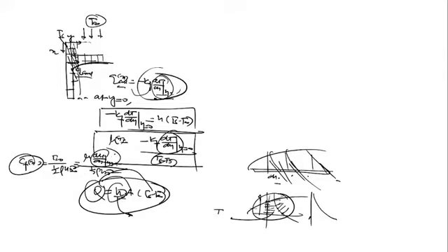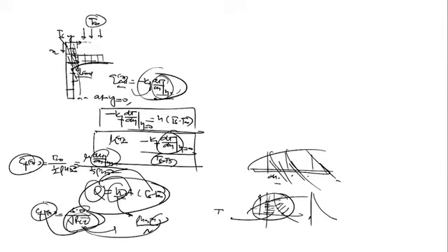But I have an alternative approach. Friction coefficient is equal to 5.0 upon under root Re x. Here it does not require any information about the velocity gradient, it simply requires the knowledge of Reynolds number, rho u infinity x over mu. At any x you can find the Reynolds number and the local friction coefficient. Yes sir?